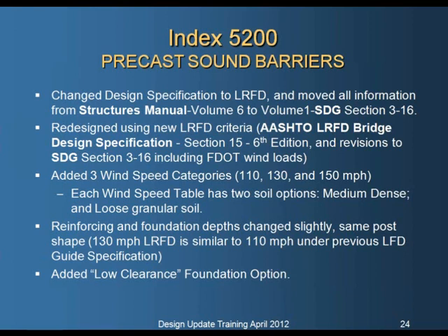So we reanalyzed our existing sound walls using this criteria and the FDOT wind loads, since the wind loads included in Chapter 15 aren't as current as those that we currently use in Florida. So it's sort of a hybrid of the LRFD load factors with the FDOT wind loads.